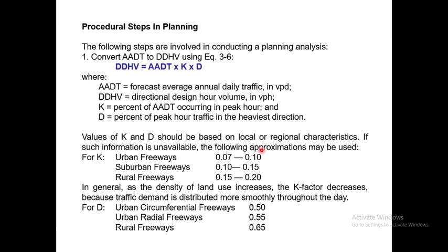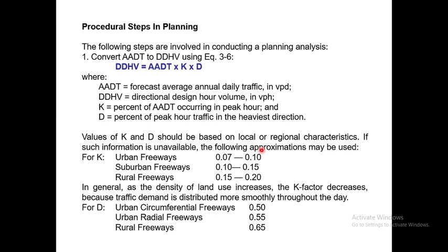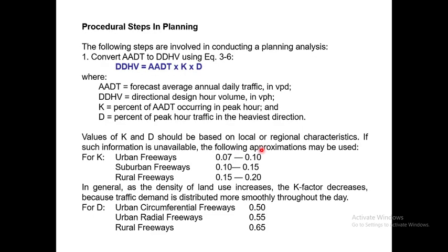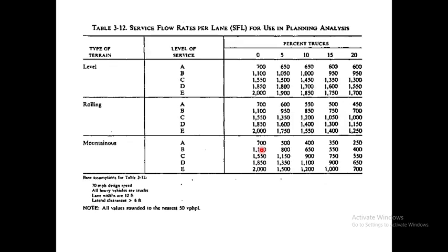Okay, so you first have to convert the average annual daily traffic to the directional design hour volume. Okay, and then convert the directional design hour volume to SF, and then use the SF for calculating the N. Very easy, exactly like the same one.